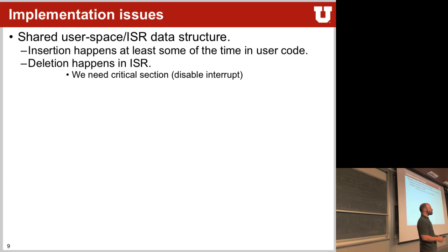Yes? You can intentionally trigger an interrupt that modifies the list. But then you somehow have to tell the interrupt that this is actually not a timer interrupt, but actually an adding interrupt, right? And then you still have to somehow give data to that interrupt service routine, which might not be easy to do, right? It is easier to just turn off interrupts, yeah. Just disable interrupts, do your modifications, and re-enable them. And if an interrupt happens in between, well, it will be handled right after.